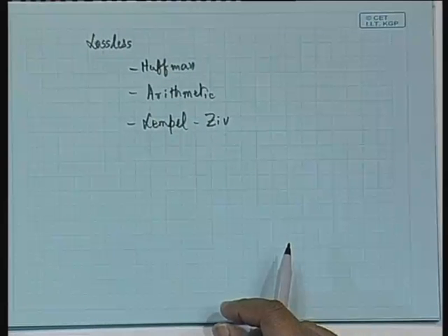So there are several such lossless image compression techniques in existence, but as I was telling you, lossless compression techniques always have some limitations, because you can achieve only a limited amount of compression using the lossless techniques, okay. And it is seen that even if you make use of a quantizer and you try to quantize the transformed outputs, in many cases our eyes will be unable to detect any major perceptual degradation in the quality of the image, although number wise it is a lossy image, okay, because if the reconstructed S cap n1 n2 array does not exactly match with S n1 n2 array, we are going to call that reconstruction a lossy reconstruction.